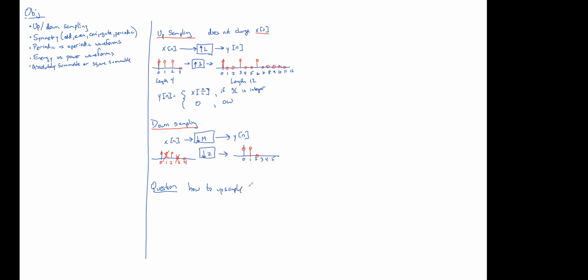I want you to have seen it someplace because it's a graduate level topic, but it's how to take a signal that has limited information and upsample it, do some filtering on it that is more exact in the frequency domain on the upsampled signal, and then downsample it when you're done. But I want you just to think about how do you upsample by, say, 1.5?